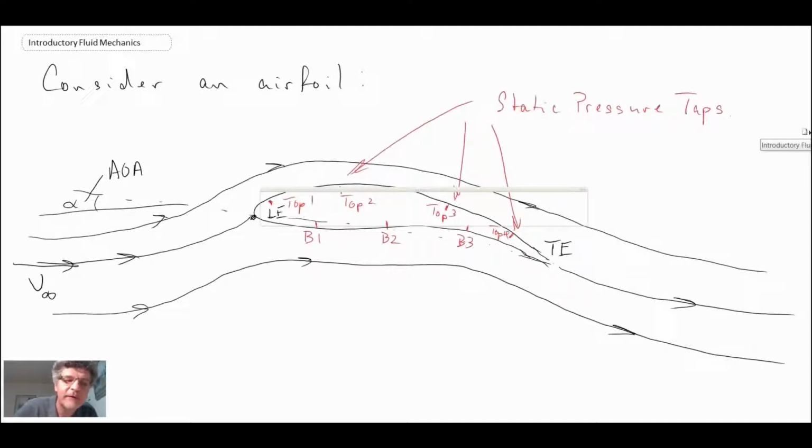So looking back at our airfoil, that's a bit of an application of Bernoulli's equation, and it gives us an idea as to how Bernoulli's equation tells us how velocity changes and how pressure changes within a flow field. So looking back at this airfoil, we would have a case where on the top, this was a high velocity and here high, and then here we have the separated flow, so you're not really seeing a lot, and that's why that tap 4 didn't change much.